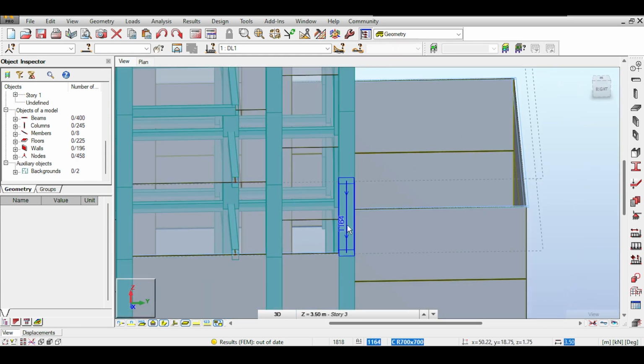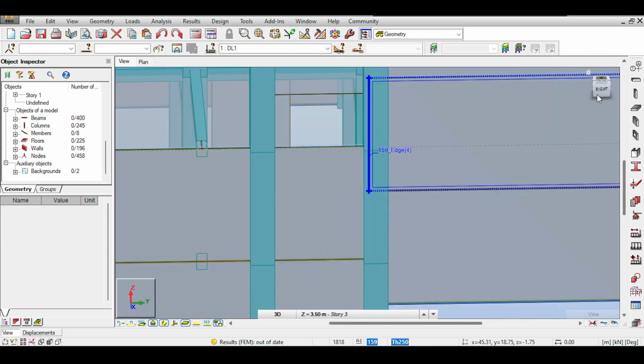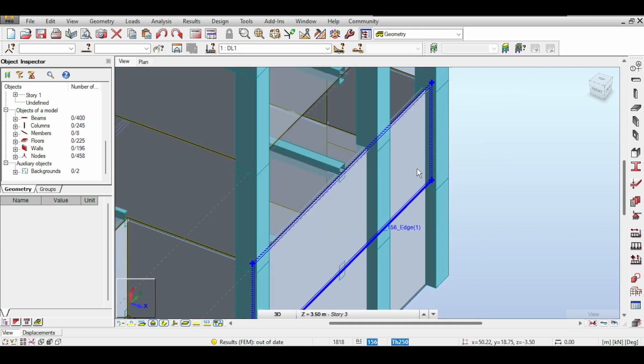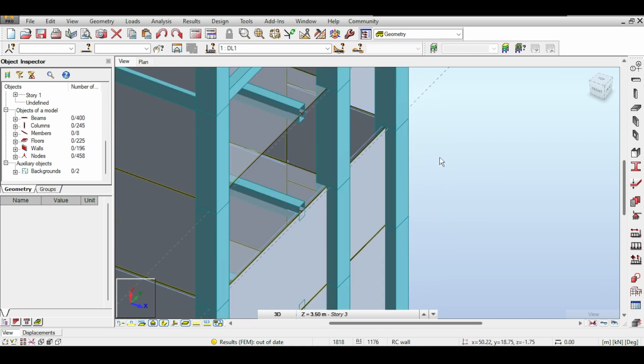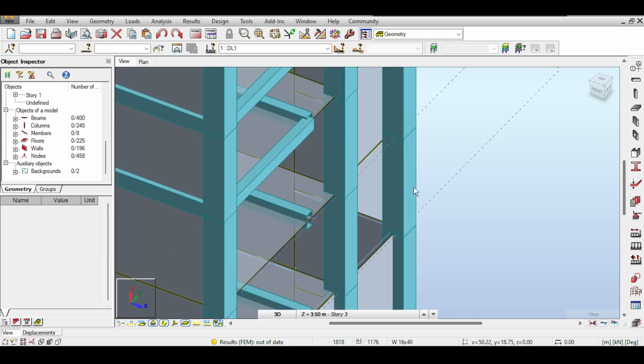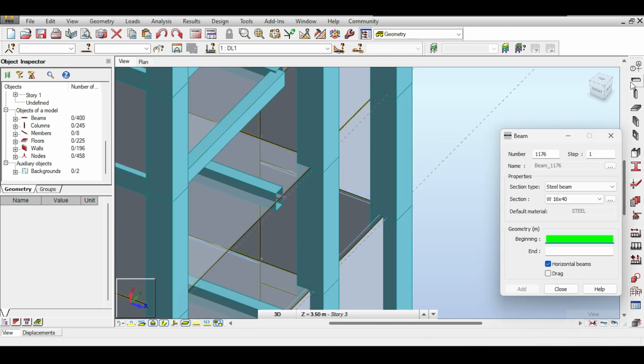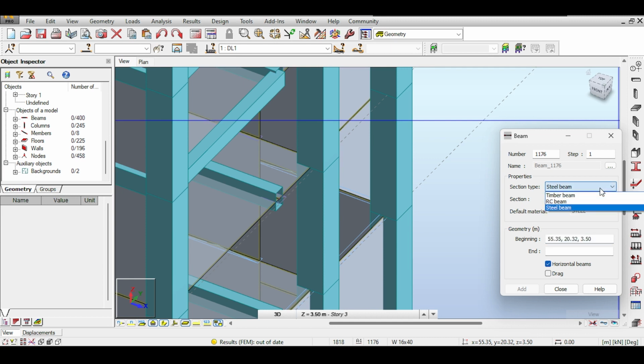Anyway, now, as I said, this staircase is resting on beams, and here it's going to rest on the retaining wall. So I don't need a beam, because I could just rest it on the retaining wall. I could cast half of the retaining wall in reality, or I could rest it on a beam. Happens, it's up to you. But you need to design it, of course, and to have correct detailing. And detailing is an amazing science. Usually what happens is we make a beam that is 200 millimeter wide and 400 millimeter or 200 millimeter high.